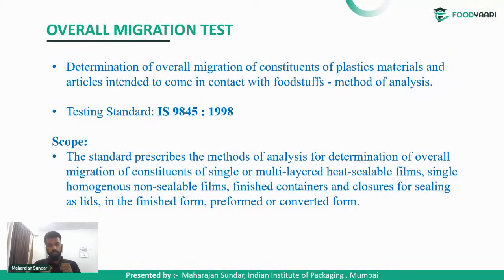Plastic has to be made to act, to move. If a plastic or packaging material has to be made, it has to be made under certain conditions, and during the process of manufacturing a packaging material, we have to add many things as catalysts. That is what I told yesterday: additives. Polymer plus additives gives us plastics. Whatever the packaging material is, without additives a proper packaging material cannot be made. These additives, such as plasticizers, flame retardants, blowing agents, there are many such additives involved in the making